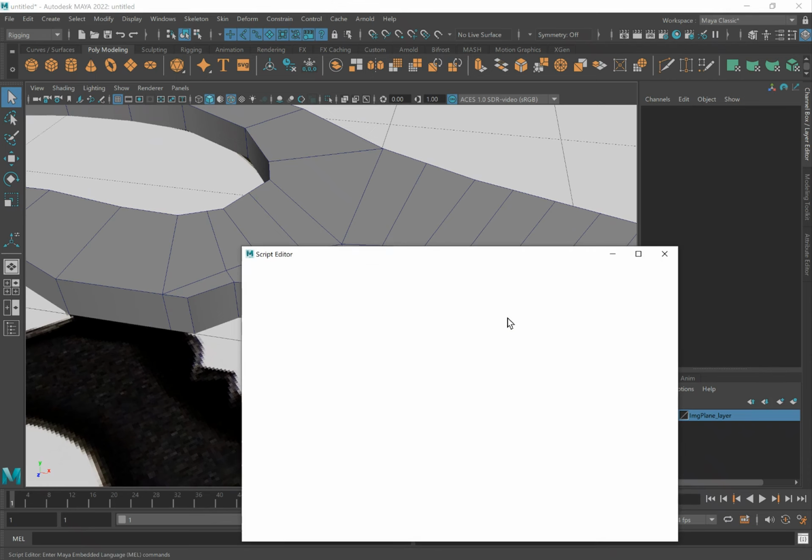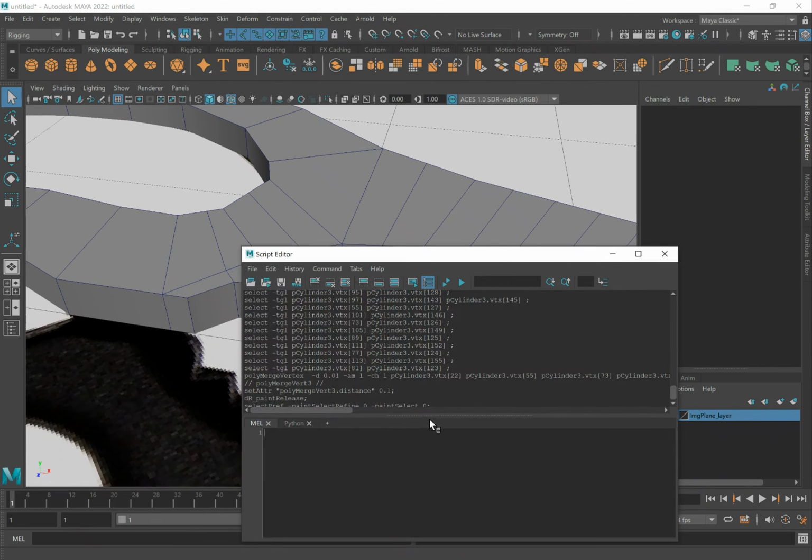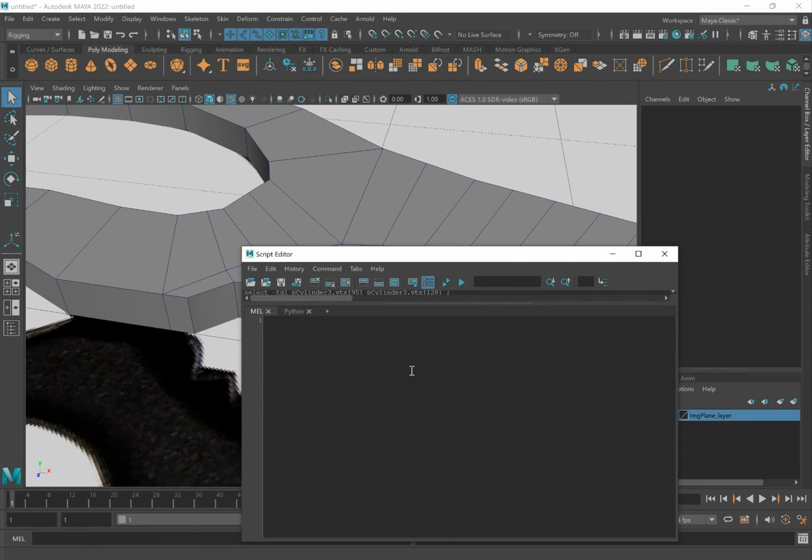So let me just key in this quickly. Okay, so 4 goes to wireframe, 5 shaded, and then alt 5 wireframe plus shaded.